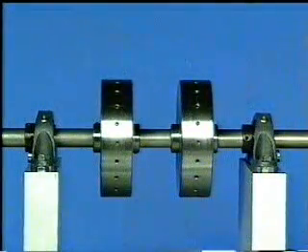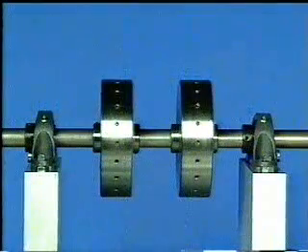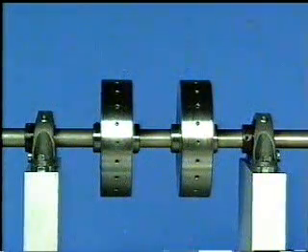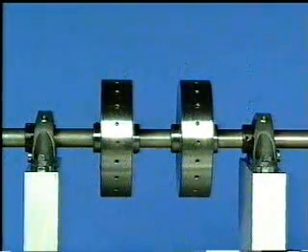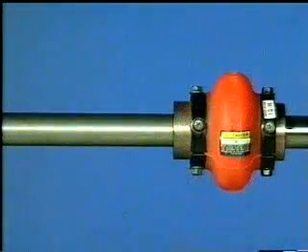Bent shafts and cocked bearings can have the same phase characteristics under certain conditions and therefore may be difficult to differentiate. Bent shafts fall primarily into two categories with very differing phase characteristics. One is a bend in the rotor between the bearings. The other is a bend in the rotor at the coupling.